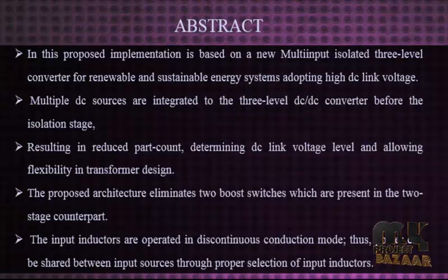The proposed architecture eliminates two boost switches which are present in the two-stage counterpart. The input inductors are operated in discontinuous conduction mode. Thus, power can be shared between input sources through proper selection of input inductors. A low voltage prototype has been designed to serve as a proof of concept.